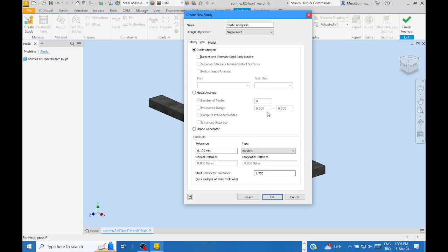When the structure comes to resonate, then theoretically the component tends to go to infinity in one direction and in the opposite direction, with infinitely large amplitudes. Of course, atomic bonding forces cannot balance such extremely large deformations, then the object breaks. We never want to have resonance. Avoid having resonance.